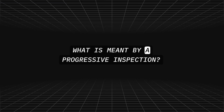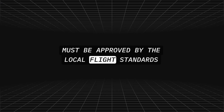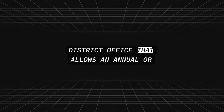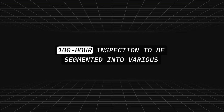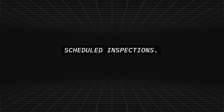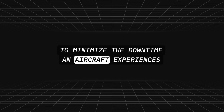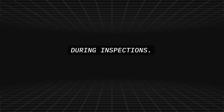What is meant by a progressive inspection? It is a type of inspection program that must be approved by the local Flight Standards District Office that allows an annual or 100-hour inspection to be segmented into various scheduled inspections. The purpose of a progressive inspection is to minimize the downtime an aircraft experiences during inspections.